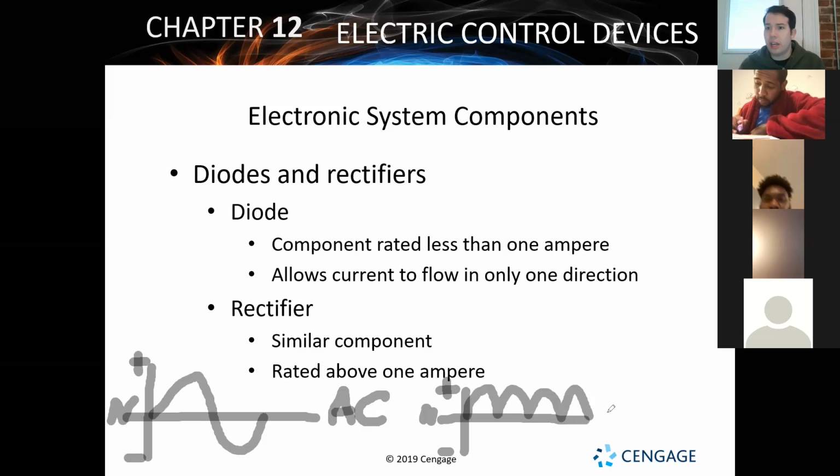Now, how this can help out is that modern systems use AC electricity and bring it all the way up to the control board as AC. The reason we use AC when traveling long distances is because it travels better over long distances. DC electricity going long distances will drop voltage very rapidly unless the wires are extremely large.